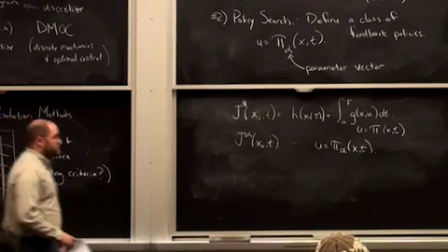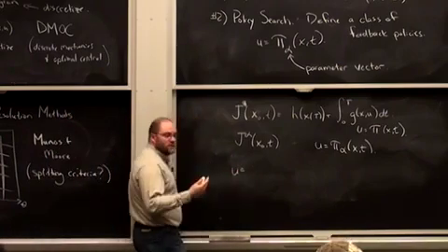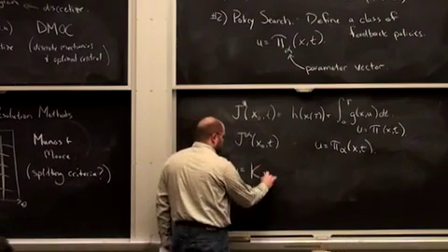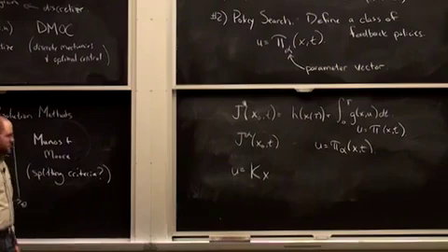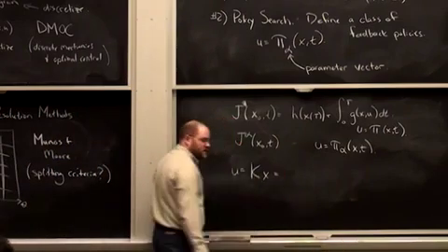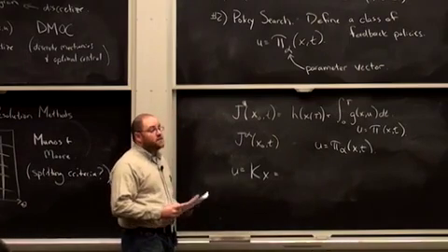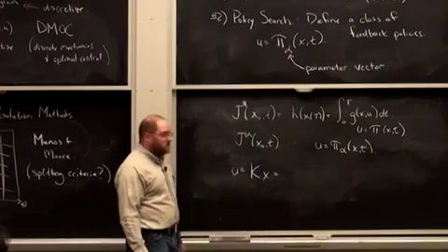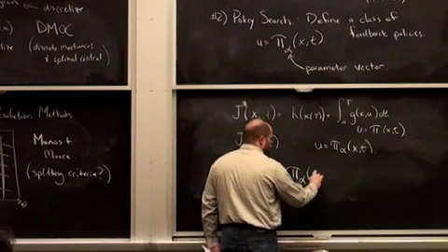So here's a couple potential parameterizations. We talked about the linear family of feedback policies, linear feedback control with some big gain matrix K. Well, that's a perfectly acceptable policy parameterization. If I want to search over the class of feedback policies that are linear, then I could call that pi of alpha, x of t.